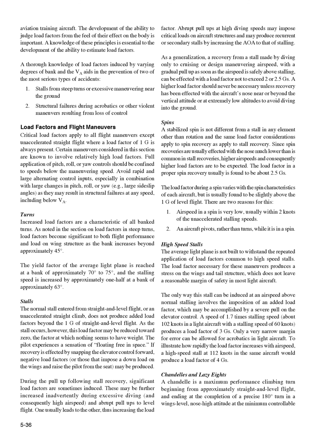A thorough knowledge of load factors induced by varying degrees of bank and the VA aids in the prevention of two of the most serious types of accidents. 1. Stalls from steep turns or excessive maneuvering near the ground. 2. Structural failures during acrobatics or other violent maneuvers resulting from loss of control. Spins. Load factors and flight maneuvers.